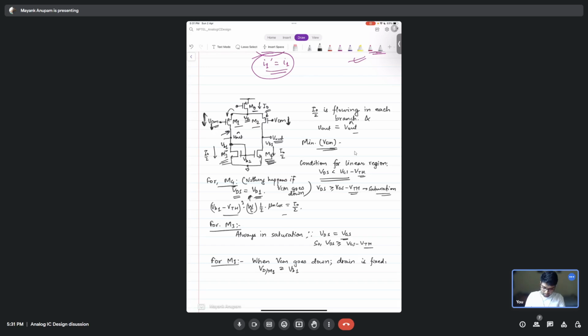Tell me, if VCM was changing, does that change the current in M3 and M4? Current will not change, sir. It should be I naught by 2 here and I naught by 2 here also.